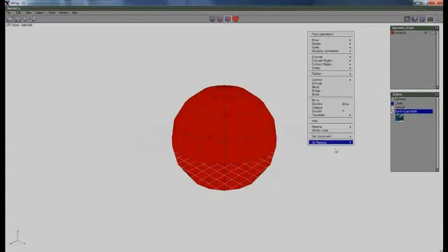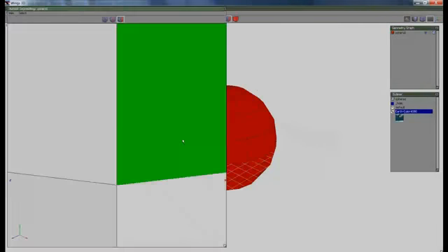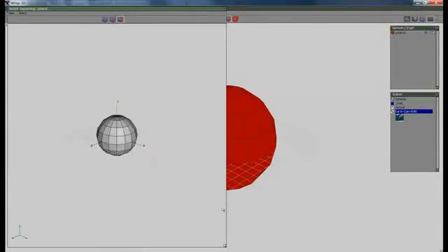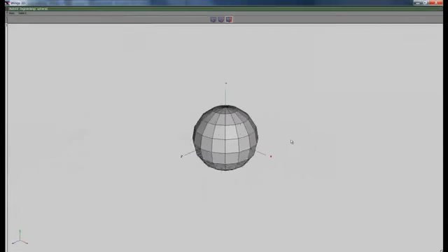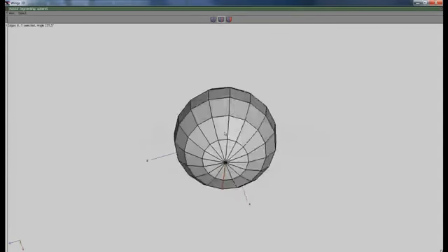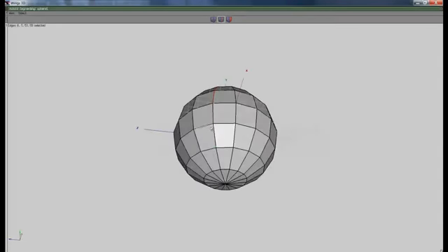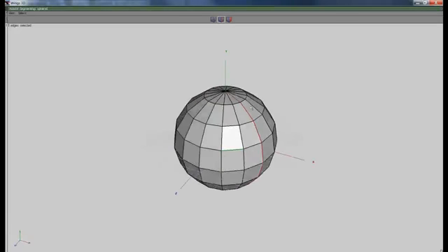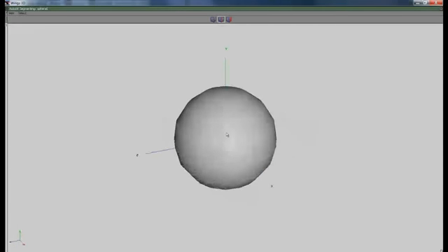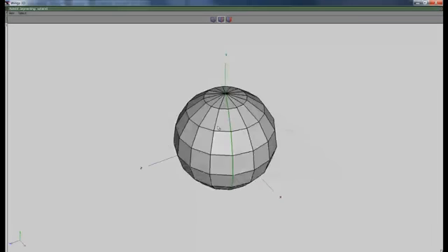So let's just select our sphere, and again, UV mapping direct. And this is the UV mapping window. And I can just select, so we obviously need a seam somewhere. It doesn't really matter where, but we need one. So I'm just going to select that like so, and mark edges for cut. And you can see that that actually became a hard edge if you go to shaded mode.